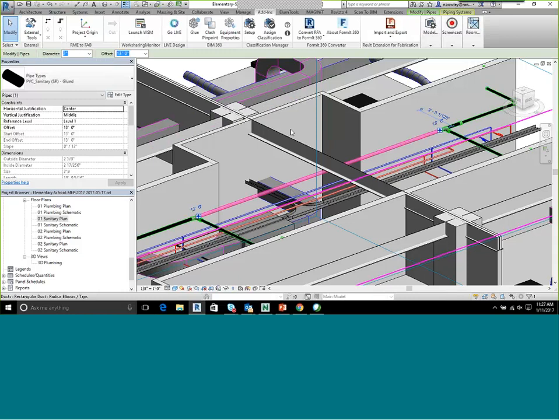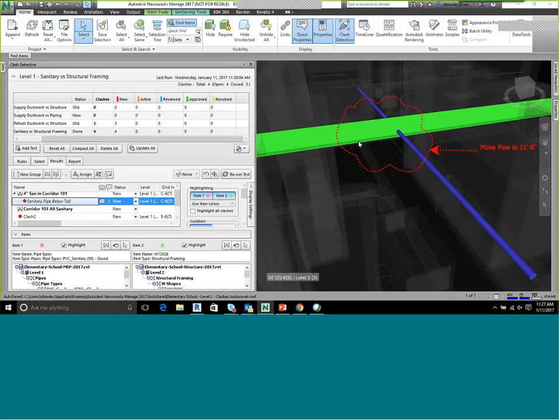When you click on that, nothing really happens. All it does is initiate the ability for that tool to function with this file. If you're working with an AutoCAD file, the command to initiate the switchback tool between Navisworks and AutoCAD is called nwload. So all you would do is type nwload in the command line in AutoCAD, hit enter, and then it would initiate that tool to function.